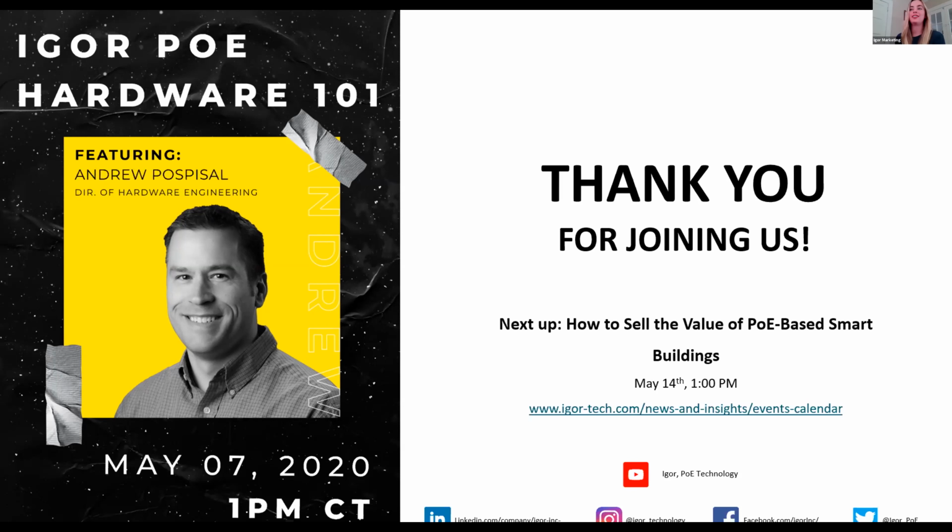Great. From Sean, he's asking if there's any integration with Honeywell's BACnet devices. We do offer a BACnet over IP add-on service. This would be at the gateway server, and so that is an additional service that can be added to our gateway software that will expose the lighting network as BACnet objects via BACnet over IP.